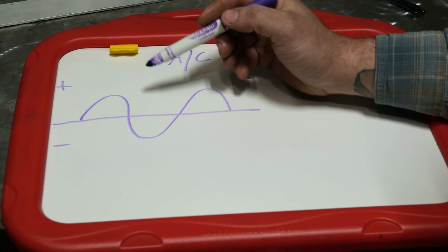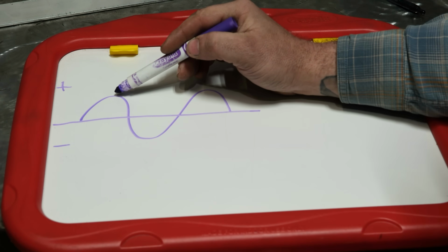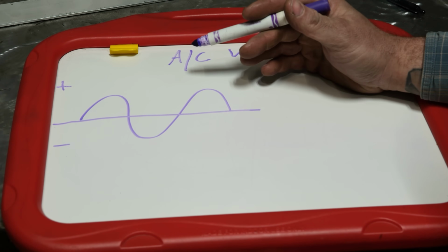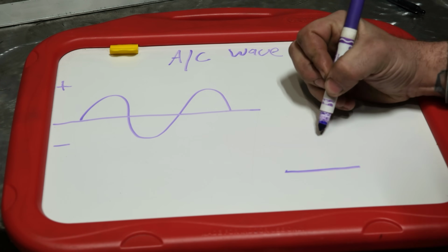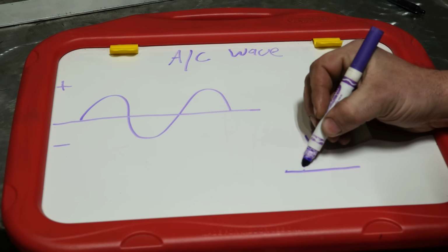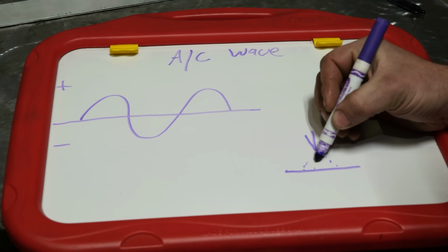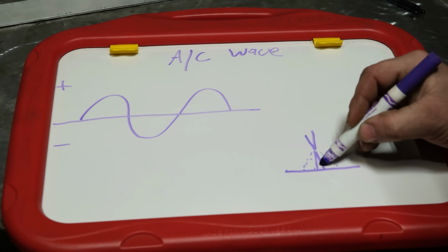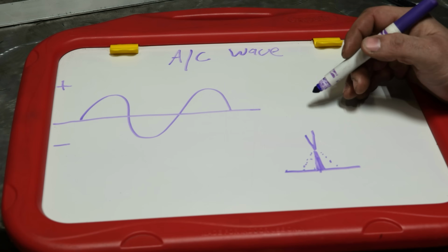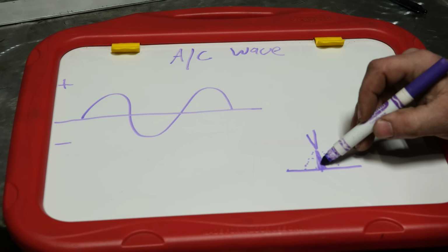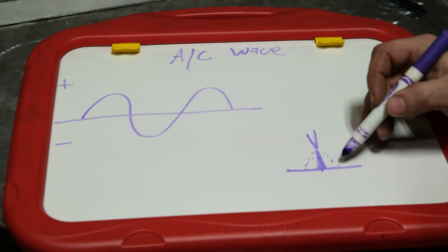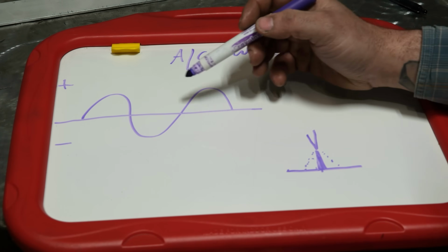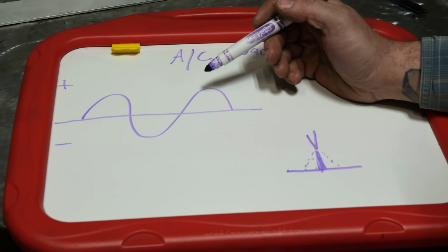It is called AC because it is alternating, technically, between positive and negative on the output. In the TIG arc, we see this as more or less you have a plate here, your TIG tungsten here. You will see on AC where electrons will jump off the plate in a wide cone back to the tungsten, and then you will also have a focused arc towards the plate. When you weld on pure DC with TIG, you only have a small arc cone. You do not have the wider arc cone of AC like with aluminum. Well, that is because we are more or less going through a sine wave of both positive and negative.